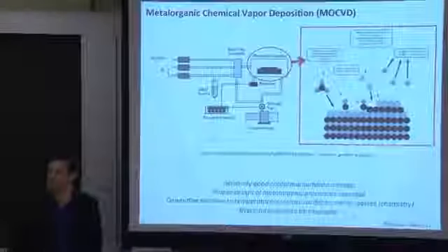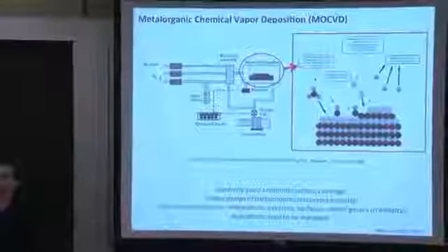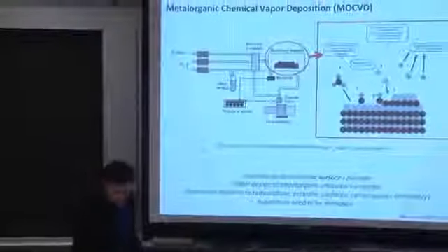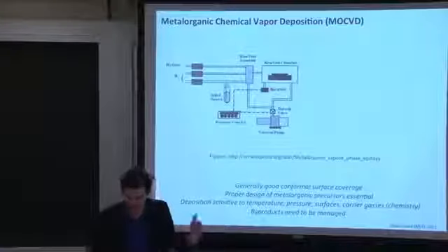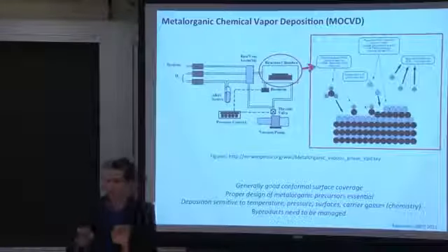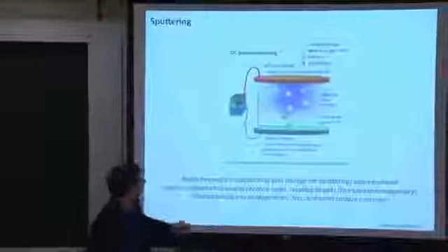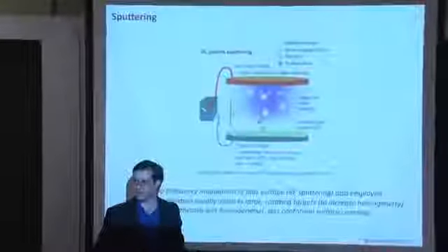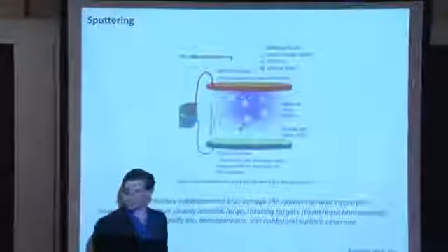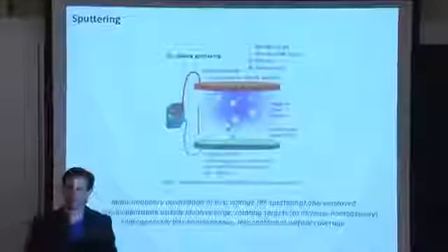Yes? And the purity quality is much better for MOCVD than it is for sputtering, right? It depends on a lot of factors. So the reason the purity of MOCVD is generally better than sputtering is because the mass flow controllers necessary to control the gas flow are specific for particular types of gases. Now in sputtering, because of the versatility of the sputtering chamber, you could take this target out and put, maybe Ashley comes along into your sputtering chamber and she puts in another target of another metal. And now you're depositing 2 different metals in the same sputtering chamber, you're going to get cross-contamination.